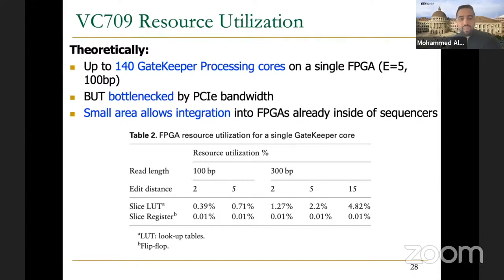So the critical path in FPGA implementation is very important here, so that you can drive a lot of these gates in parallel. Sometimes you cannot apply the VCC or the ground to a large number of gates, and that's specified or controlled by the total critical path or the worst delay in any of the input signals, for example. So you may need to use pipelining techniques to reduce this critical path, or you reduce the number of replications. These are all challenges when you implement a parallelized algorithm in FPGA, or you would like to fully utilize all resources you have in the FPGA.